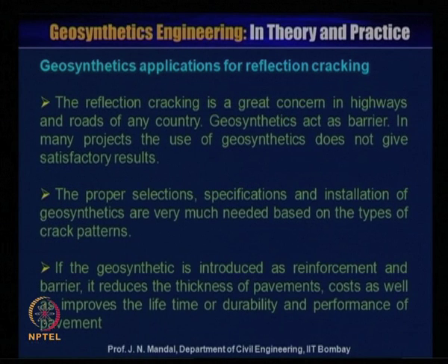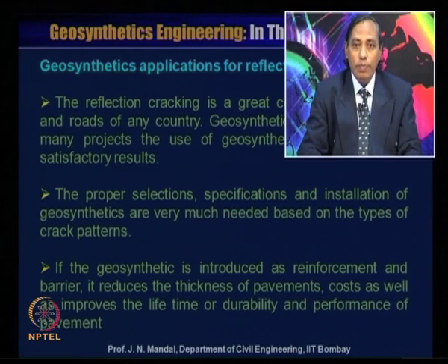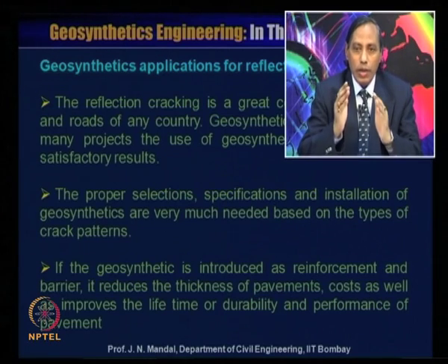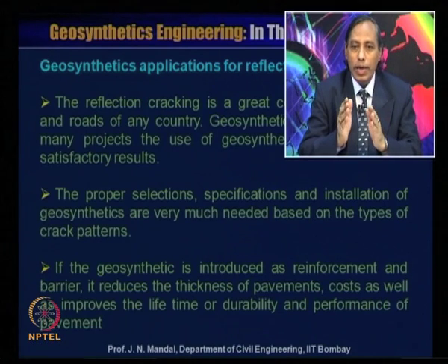Next, geosynthetics application for reflection cracking. Reflection cracking is a great concern in highways and roads of any country. Geosynthetics act as a barrier in many projects. The use of geosynthetics does not always give satisfactory results, because proper selection, specification and installation of geosynthetics are very much needed based on the type of crack pattern. If the geosynthetics is introduced as reinforcement and barrier, it reduces the thickness of the pavement. I showed you in my earlier lecture how the thickness is drastically reduced due to the presence of the geosynthetics material. It also reduces cost and improves the lifetime or durability and performance of the pavement.